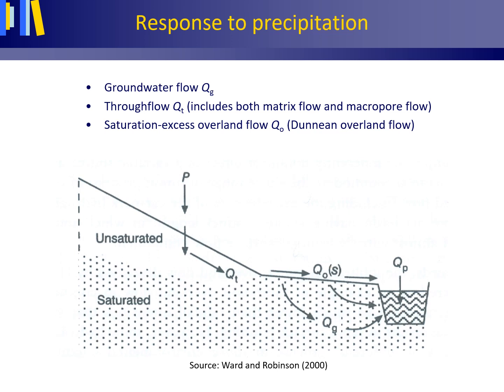This type of overland flow is fundamentally different from an earlier discussed type of overland flow, where the rainfall intensity in millimeter per hour exceeds the soil's infiltration rate in millimeter per hour, as can be observed on bare or crusted surfaces with reduced infiltration under arid or semi-arid climates. This type of overland flow is called infiltration excess overland flow or Hortonian overland flow, after the earlier mentioned American ecologist and soil scientist Robert E. Horton.